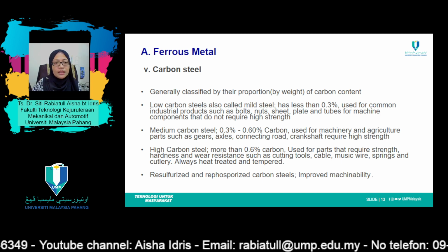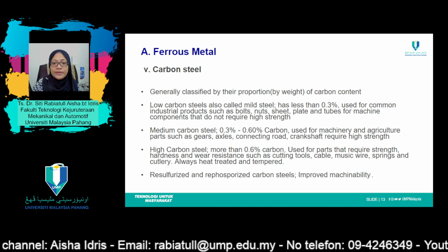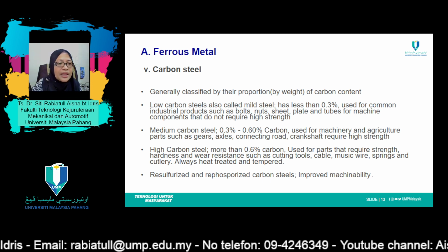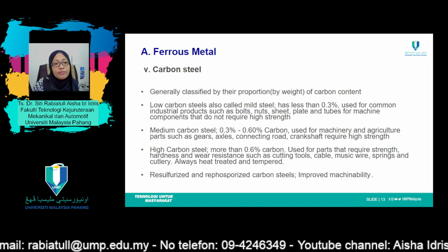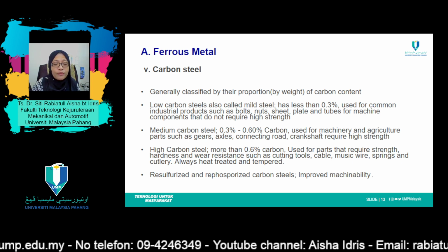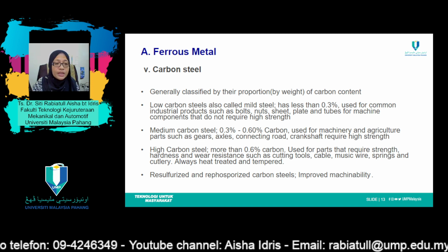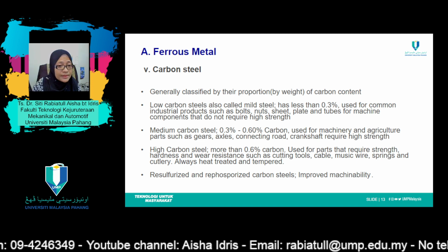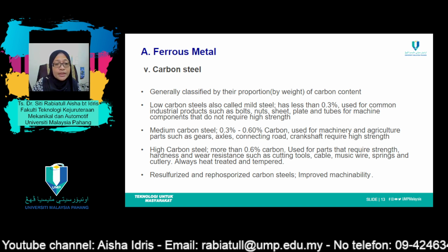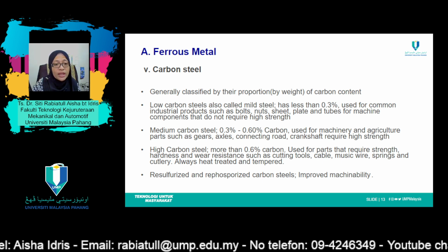For medium carbon steel, the concentration of carbon is between 0.25 and 0.6 percent. These alloys may be heat treated by austenitizing, quenching, and then tempering to improve the mechanical properties. They are most often utilized in the tempered condition, having a microstructure of tempered martensite. The plain carbon steels have low hardenabilities and can be successfully heat treated only in very thin sections and with very rapid quenching rates.